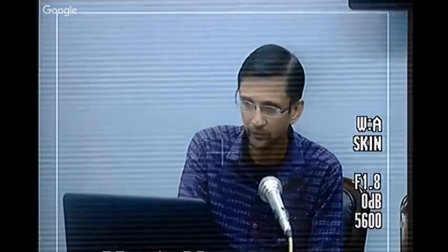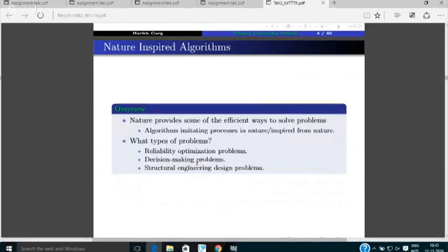So we usually take the Weibull function. Weibull gives a bathtub curve. The bathtub always represents this because, say, I just want to buy this marker newly, then the life of this marker is 1 hour for the newly bought product. After that it slows down for the next hour, and after that it decays. So the graph is a U shape. Firstly it is high, then decreases, then constant, and then there is a peak level. So that is a bathtub.